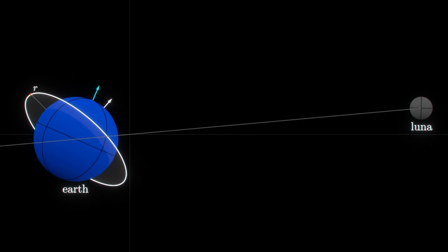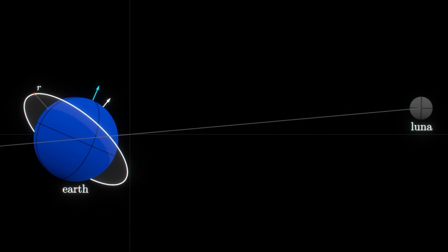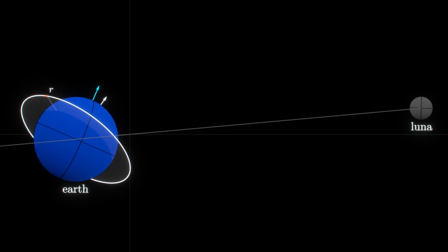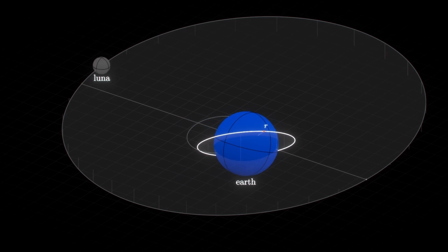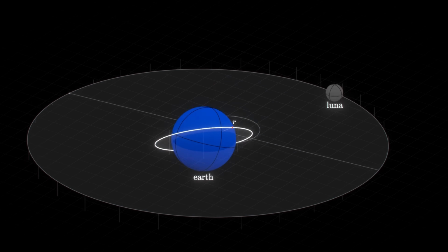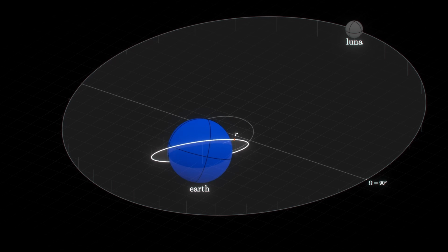savings? Because the target orbit precesses, it will periodically realign with the lunar orbital plane, so the obvious strategy is to choose an orbit whose nodal precession lines up with the moon's orbital plane as often as possible. The complication is that the moon's orbit also precesses under the influence of the sun, with a cycle period of roughly 18.6 years. When the lunar longitude of the ascending node is at 90 degrees, call that the start of